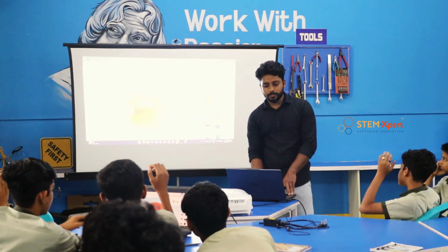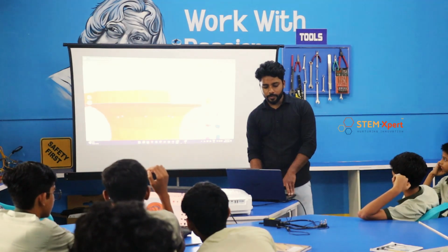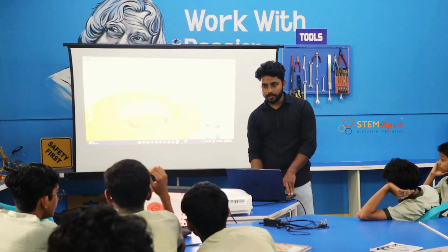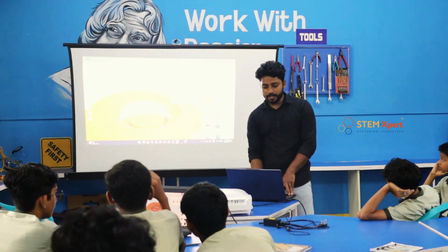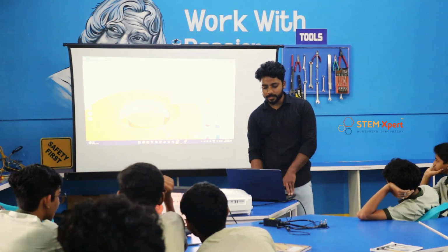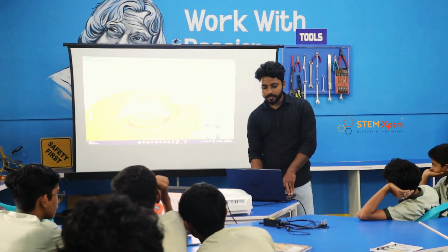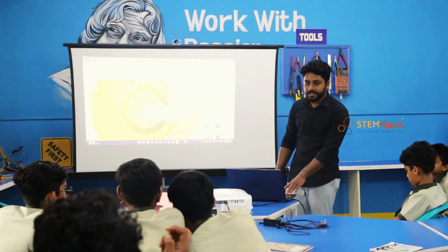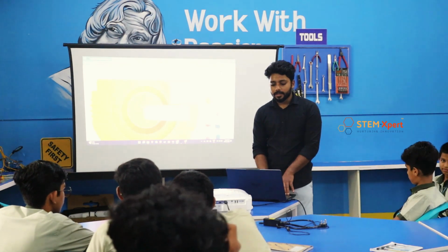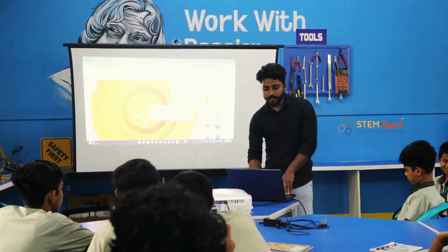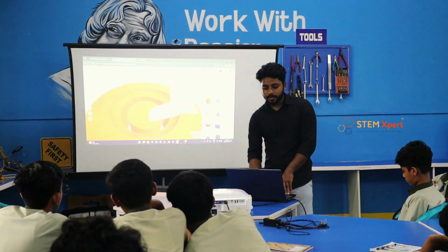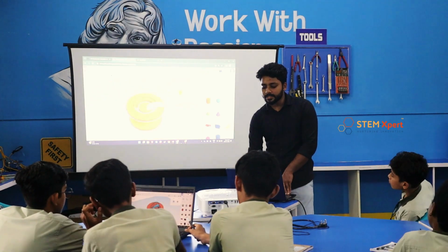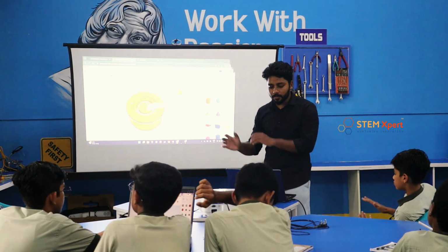Now click on this align tool. After selecting these two objects, click on the align tool. You can use this one, and also like this. Fine. So it will be like this. At first we are making the object like this. We are placing the object like this, and then we are making some changes here. Go to the front view, go to fit view, and in here you can lift this object like this, and then rotate it. Just rotate it like this. Just place this object like this, and when you see it in the front view, you can see it is somewhat matched up.